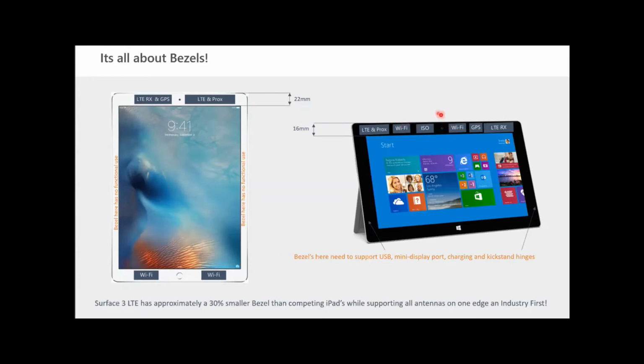So Bluetooth and Wi-Fi don't really coexist too well unless you've got something like 30 dB of isolation, believe it or not. A lot of the Wi-Fi chips these days say they can deal with 15, but not really. You need roughly about 30 dB. So we've got some technology in there to help with that 30 dB isolation requirement. Basically, without that, we're down in the 12 dB region. So yeah, we've got some nice inventions there that help with that.